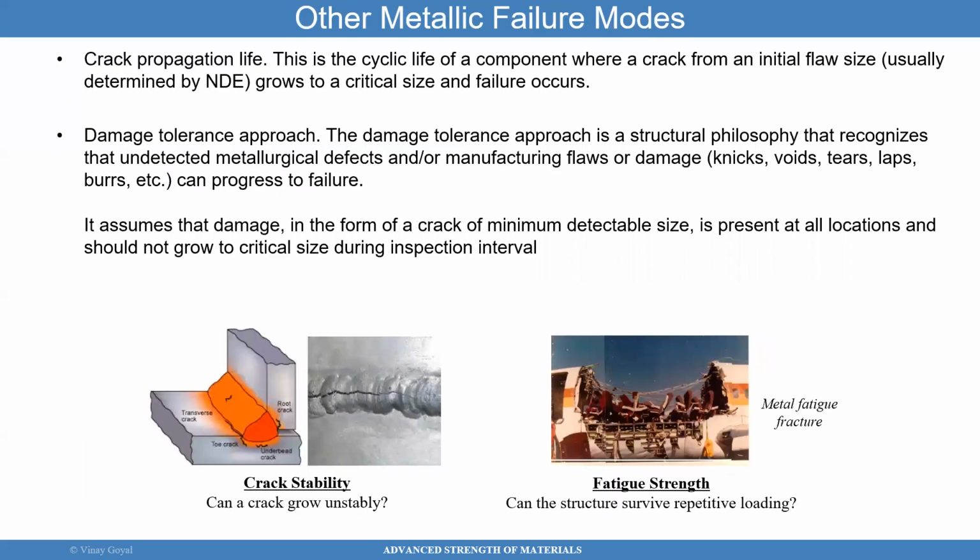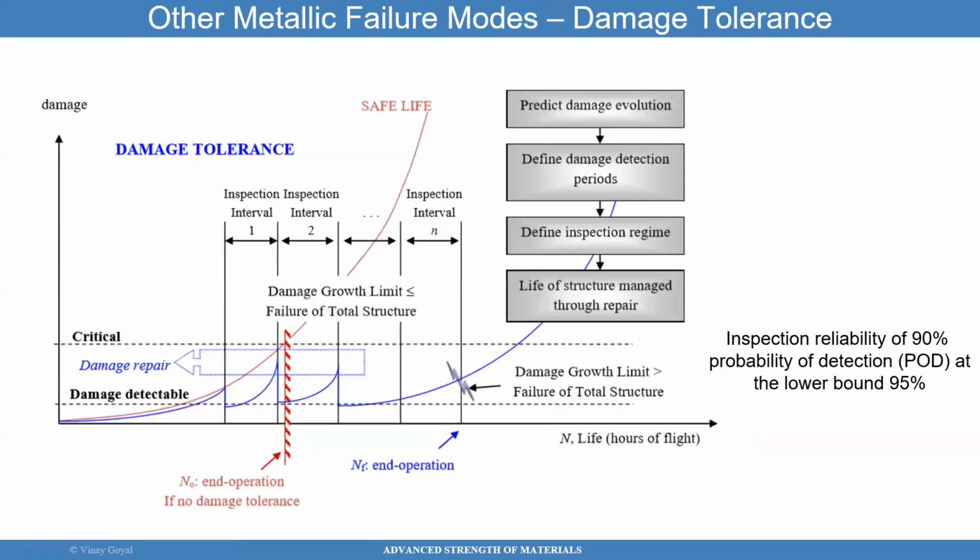We'll cover damage tolerance approaches, which means there's an initial crack that's not something you find, and that crack could propagate to failure. So that's an issue that should be considered as well. And we'll cover some concepts on fracture later in this course, and how you prevent aircraft from having a flaw propagating to failure.